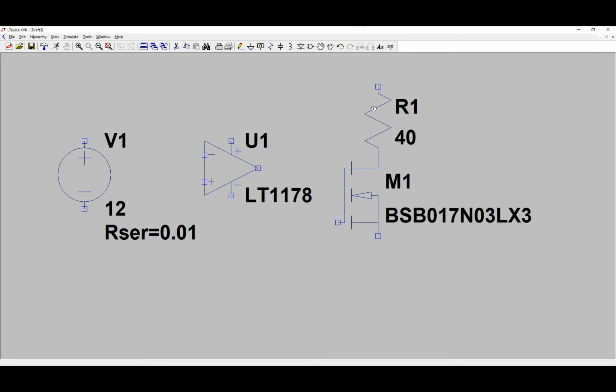Now we will connect the LED, and we will connect the sense resistor. So the sense resistor is actually limiting the current and controlling the LED. So what I have here is just a very basic circuit that will limit the current. So how it is working: the MOSFET is opening, and there is a flow of current from the VCC to the ground, and here the LED, so the LED will get the current.